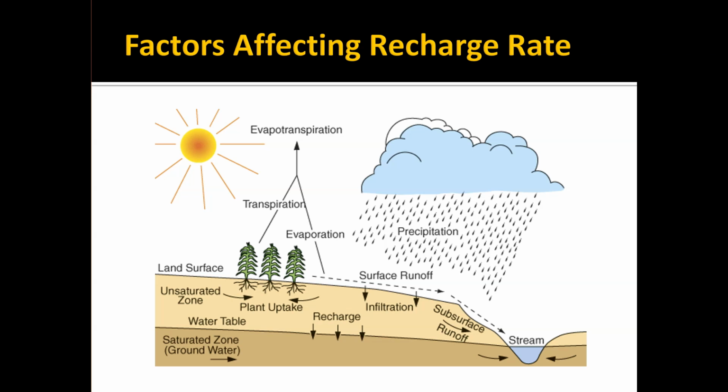So in a lot of cases, you'll just assume a constant recharge over your model domain. Sometimes you'll break up your model domain into different regions based on its slope and land use and vary the recharge. Other things can affect recharge if you're doing irrigation and applying a lot of water to agricultural land. That can lead to increased recharge.